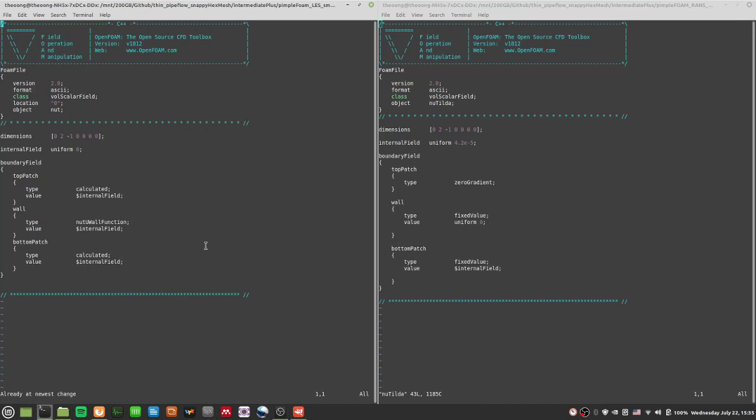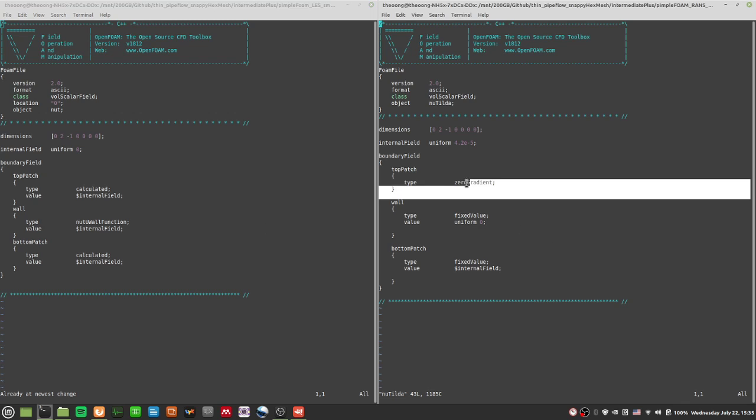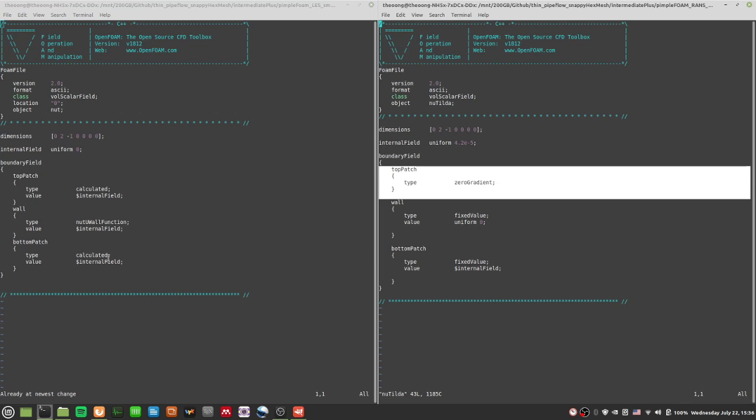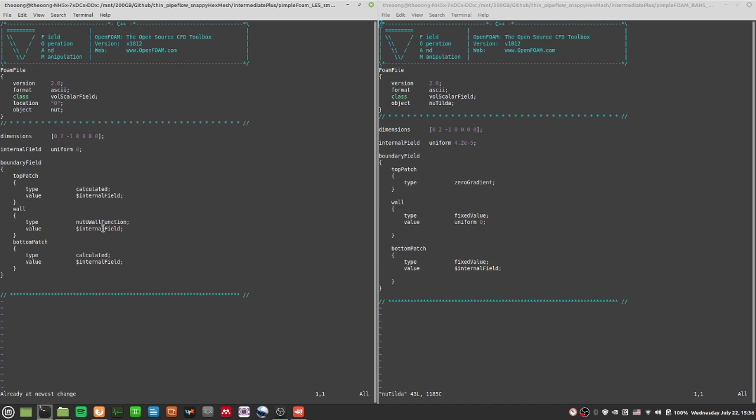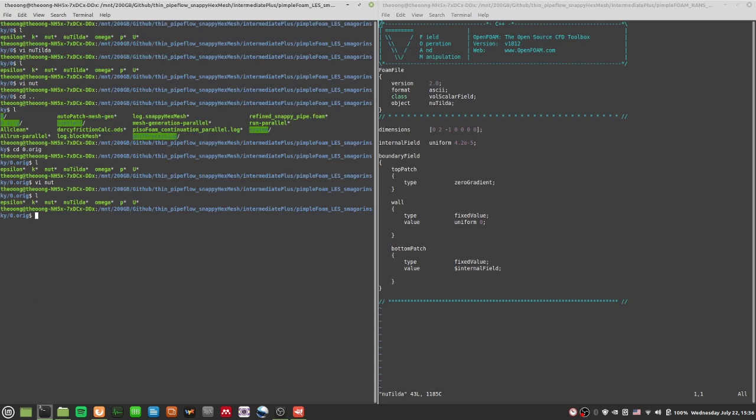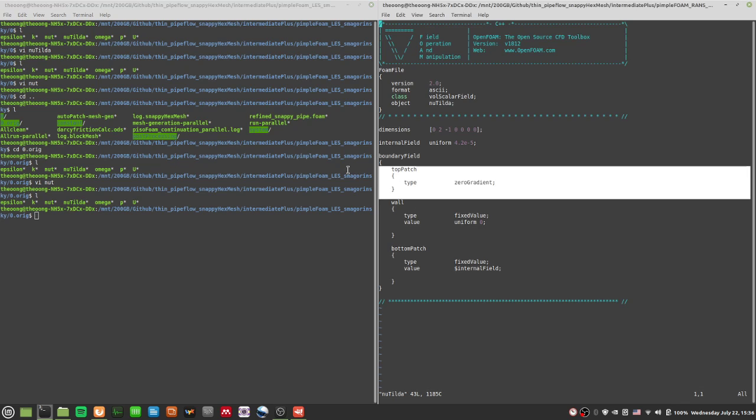Okay, so we're gonna continue where we left off in the last video because we are talking about the Smagorinsky model. Just want to start by putting in the correct boundary conditions first, because the Smagorinsky model likes to operate on this variable nu t rather than k, epsilon, nu tilde, and omega. Actually, all of these you can kind of ignore. You only need nu t, p, and U for the Smagorinsky model. You don't really need any other boundary conditions there.